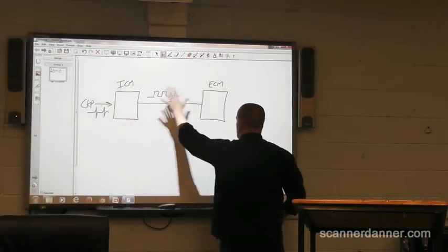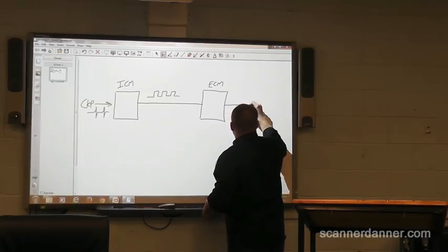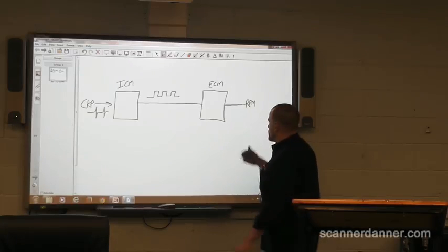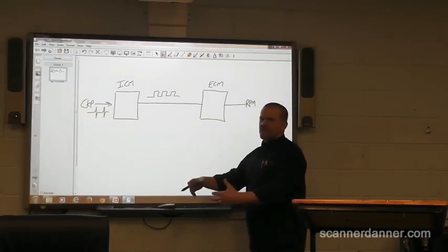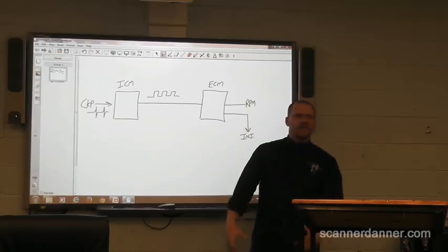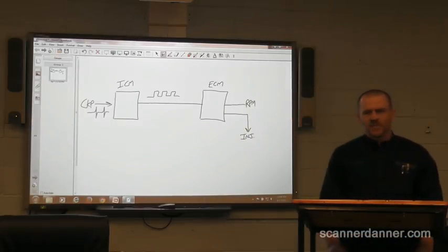The engine computer takes that signal and calculates the RPM. It also tells the computer piston position and location, and some of the things the computer will do is control the injectors based off of this on-off square wave. Okay? Questions so far?